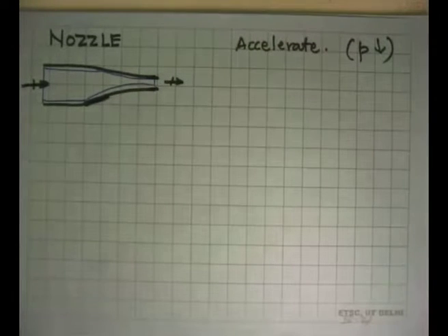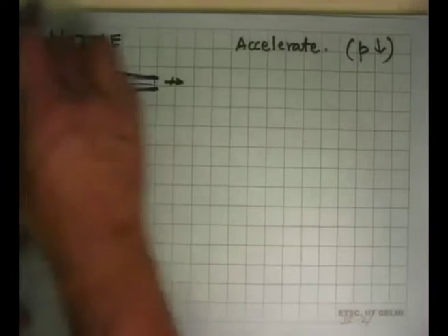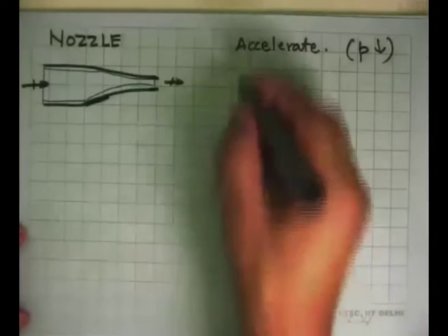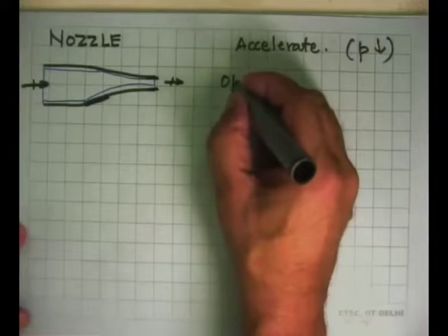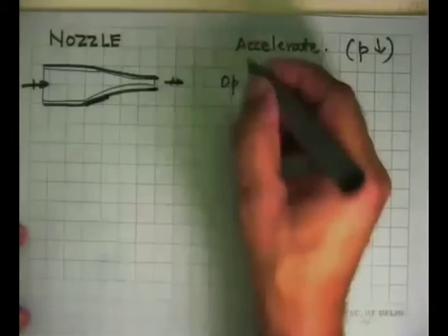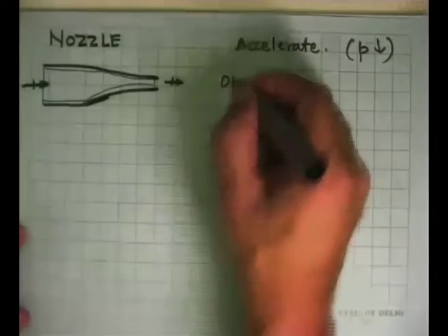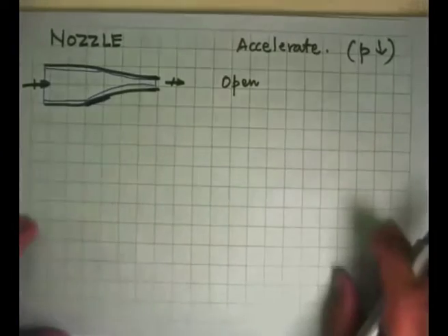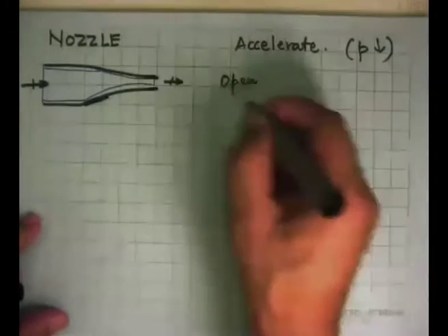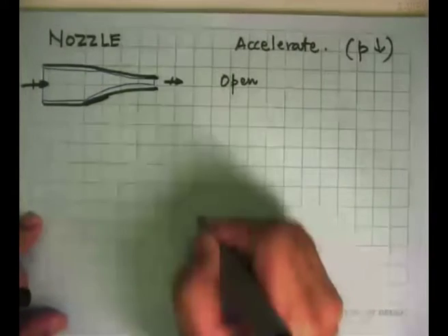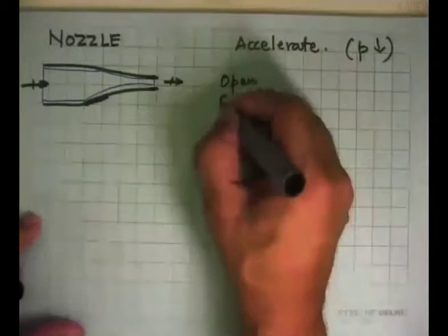Once we have made the system boundary, we see that there is something moving in, something moving out. So our first step in the analysis is to decide what the system boundary is. We did that. Whether it is an open system or a closed system. This is an open system, and then we say, well, now I have to apply equations which are the control volume equations.